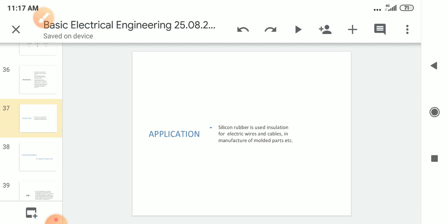What is the use of the liquid insulating material varnish? This varnish is applied on the transformer windings to prevent short circuit from one winding to another winding. We need some coatings or varnishes for impregnation processes, like that. All those things, these liquid insulating materials are very much used.